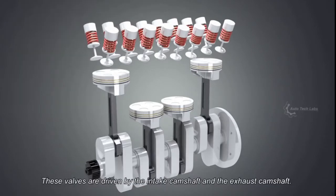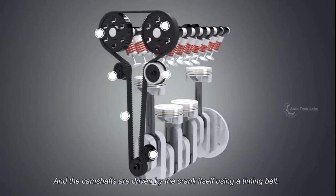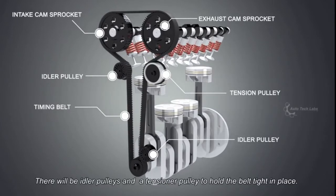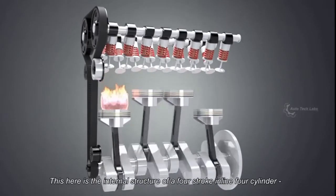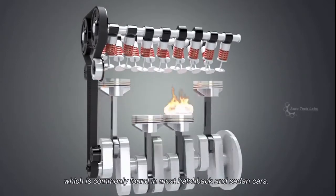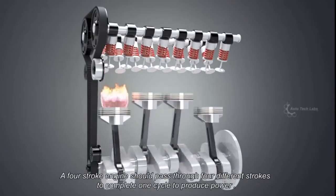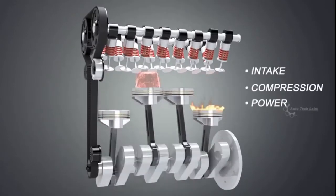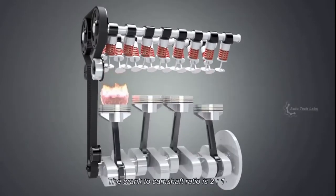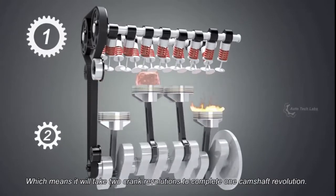These valves are driven by the intake camshaft and the exhaust camshaft, and the camshafts are driven by the crank itself, using a timing belt. There will be idle pulleys and a tensioner pulley to hold the belt tight in place. This here is the internal structure of a 4-stroke, inline 4-cylinder, DOHC engine, which is commonly found in most hatchback and sedan cars. A 4-stroke engine should pass through 4 different strokes to complete one cycle to produce power. They are intake, compression, power, and exhaust stroke. The crank-to-camshaft ratio is 2:1, which means it will take 2 crank revolutions to complete one camshaft revolution.